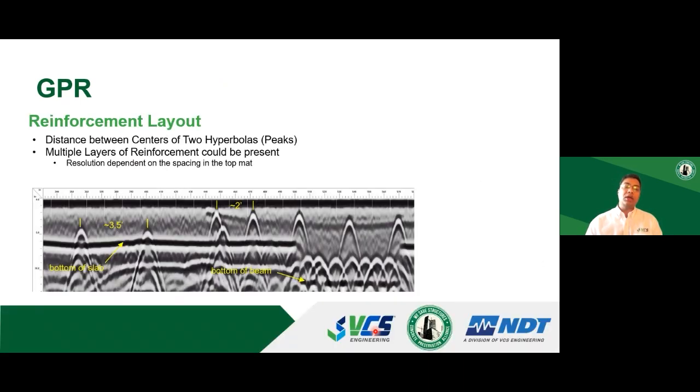In addition to concrete cover, it can tell you the rebar spacing or how many mats of rebar are present. For an experienced eye, it can also tell you if post-tensioning strands are present, or what the distribution of those rebars is. And it can help you establish a really good layout for corrosion rate measurements or other techniques.